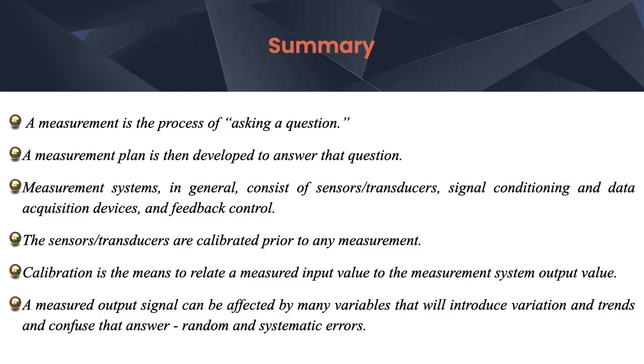Calibration is the means to relate a measured input value to the measurement system output value. A measured output signal can be affected by many variables that will introduce variations and trends and can confuse the answers, and all these errors can be categorized as random and systematic errors.